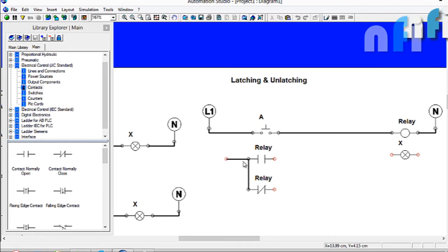Okay, so I was talking about the latching. So I'm going to give this line neutral. Sorry, this supply I'm going to give it a live. This is common. All right, so let me just write here once. This is common. This is NO. This one is NC. So this common is connected to line, and this NO is connected to a terminal which you want to latch. Sorry, it is connected like this.